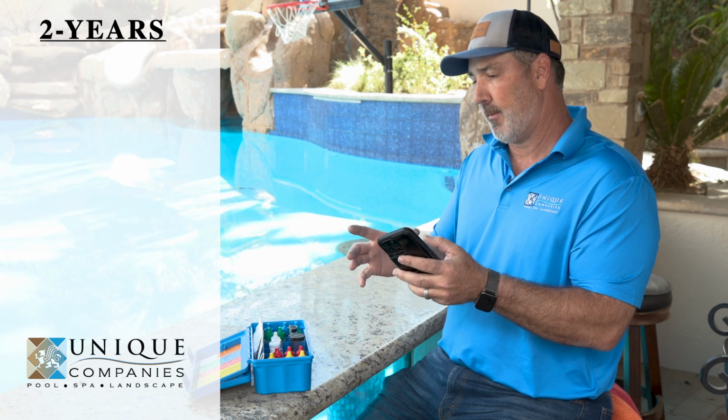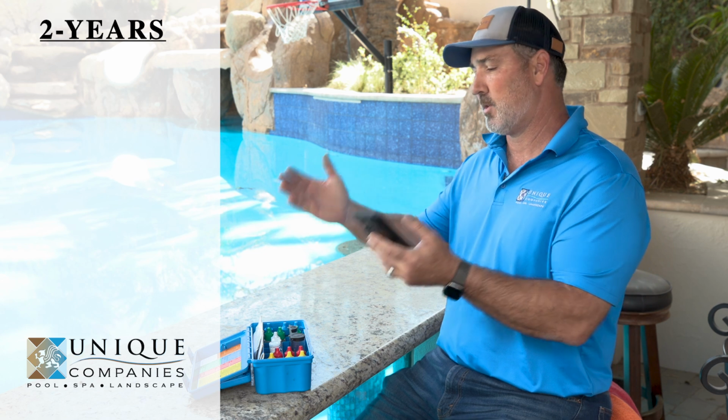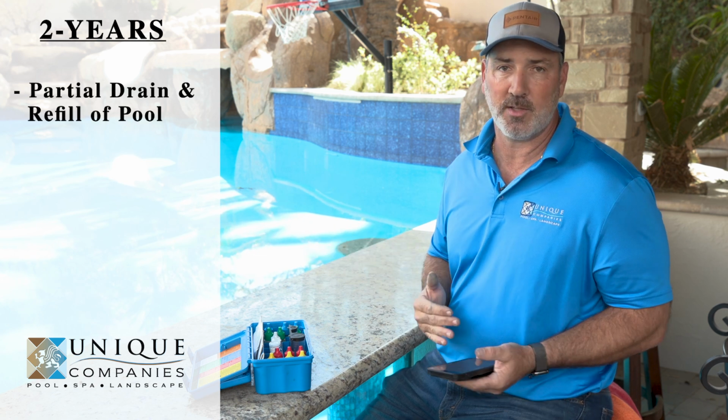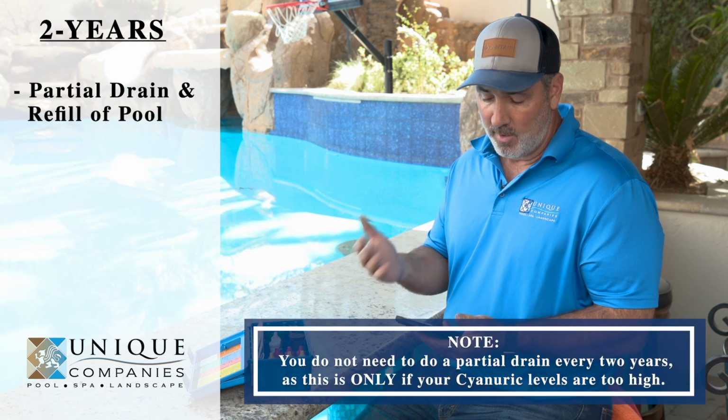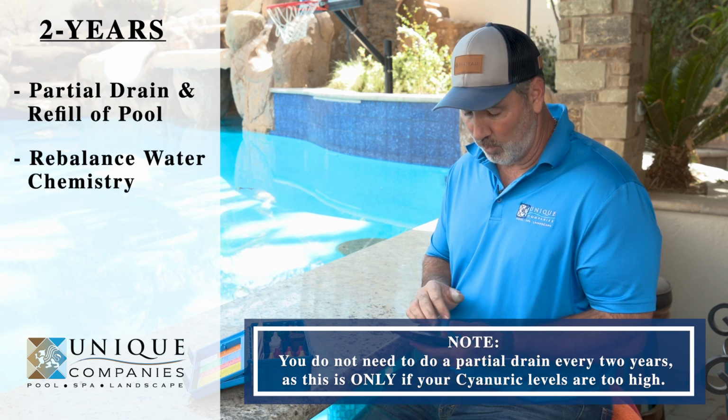Every 2 years, if you are using a cyanuric or a stabilized chlorine dispensing system, that's one of the chlorinators that you drop the tabs into, your cyanuric levels, as we talked about in Pool Chemistry 101, are going to be up over 100, and you're going to need to do partial drains of your swimming pool. So every 2 years or so, drain your pool water, refill the pool, and rebalance the pool.